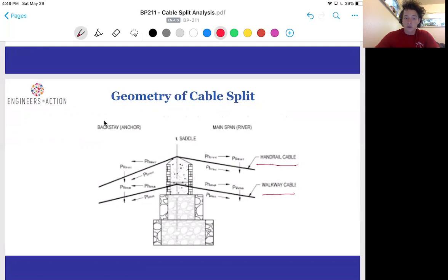Because these force vectors are at such different angles, it can potentially make a very large difference. For example, in the same problem as above, with only splitting of the cables, I can improve my factor of safety for uplift on the high side to 1.58 from 1.3.